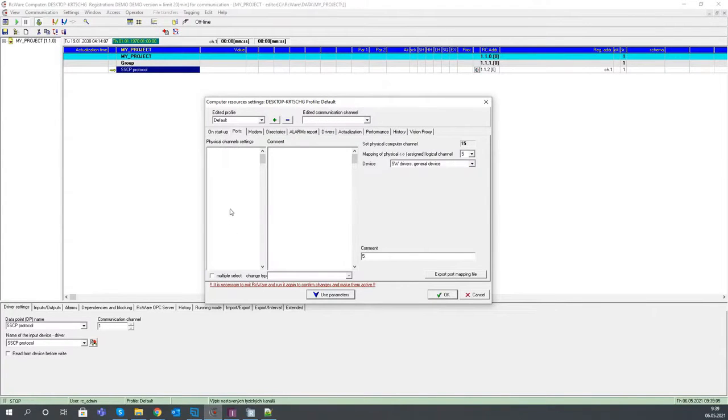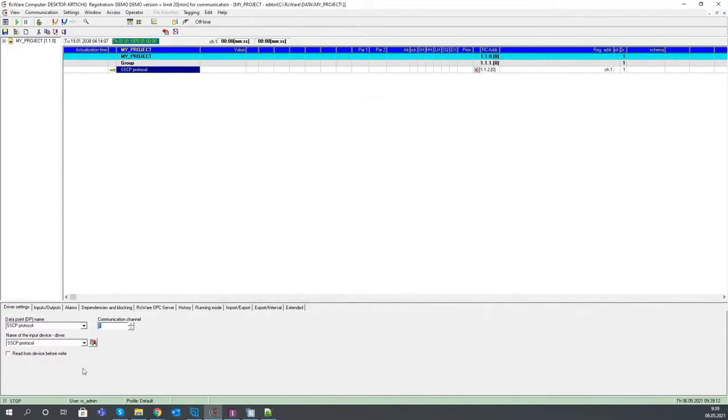If we have a channel which is not defined as a software driver and we try to use it, like here, there should be a problem later in the communication because the communication channel won't be recognized and data cannot flow from SCADA to the outside world. So I will stick to the setting which makes sense and use the communication channel of 1.